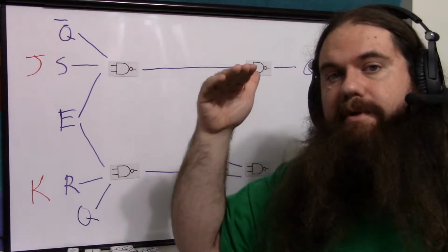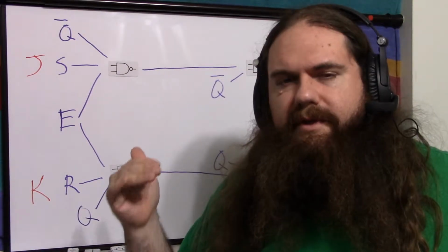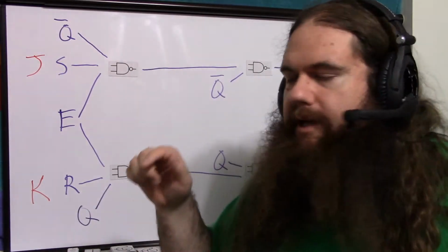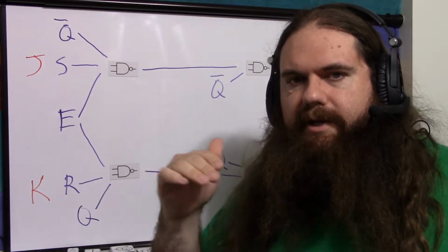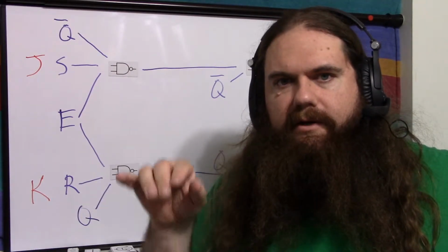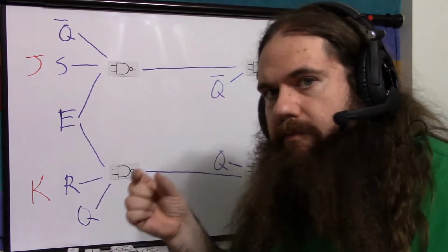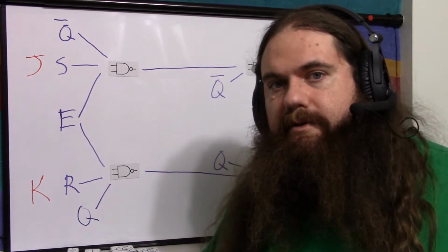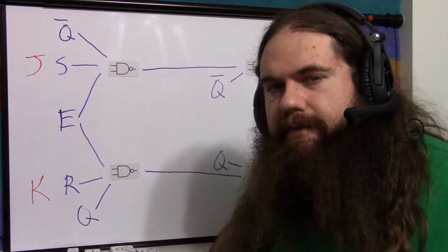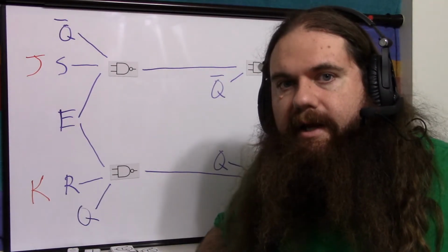At the bottom, it has to be, if you're using the serial arrangement, like NPNs, you would have your final NPN be the enable one, because obviously it has to be shared, and after that you can't split it again once you join the signal. So you can actually do it with 9 transistors. You basically just add a transistor for Q and Q naught to the existing gates, and that's all you do.